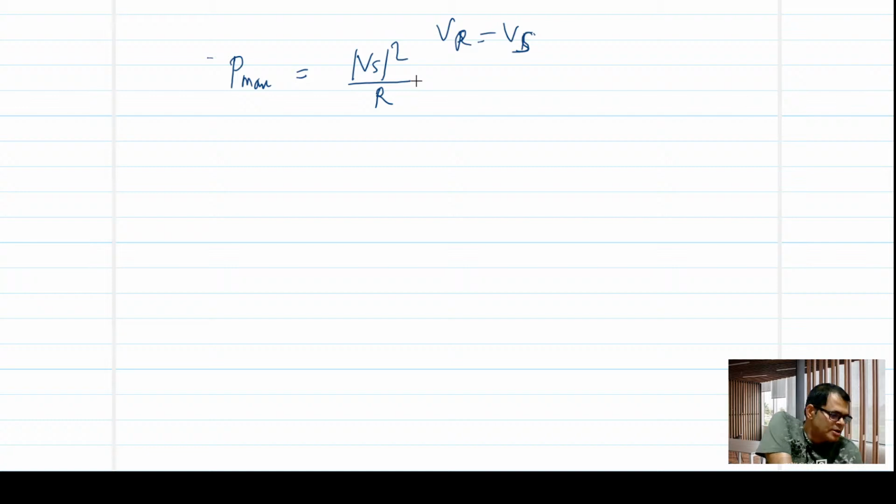Because see, whenever you have a pure quadratic equation, obviously the roots will be complex conjugate. Otherwise, it will be factored into two first order systems. For example, s square plus s plus 1 is a pure quadratic. You cannot factor it into two first order systems.